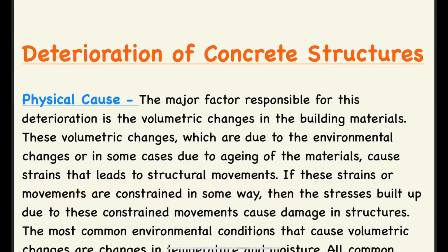And if there is structural movement in any structure, then concrete or the structure is bound to be weak. So it's a basic principle of civil engineering. Just remember the tension forces which are responsible for this. Tensile forces. If these strains or movement are constrained in some way, then the stresses built up due to these constrained movement cause damages in the structure.